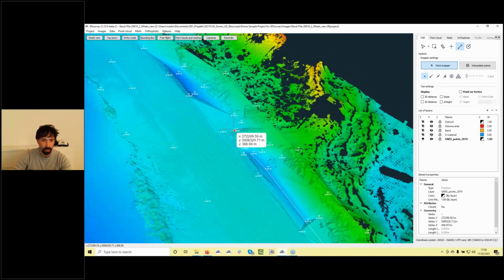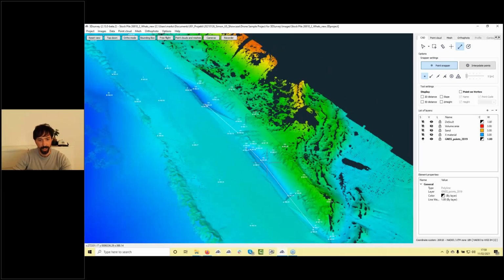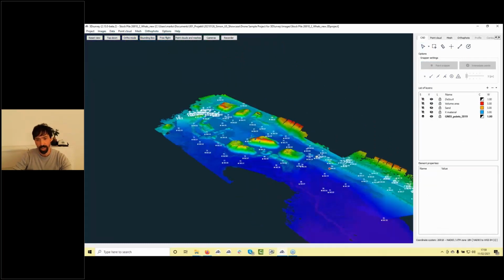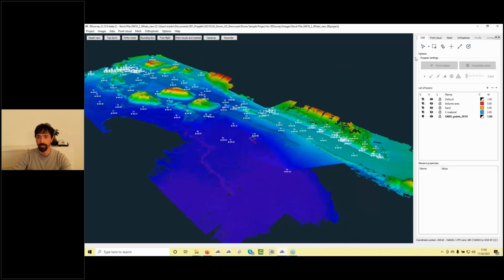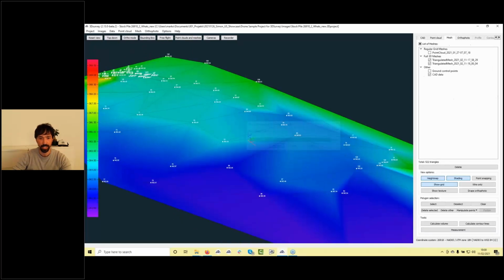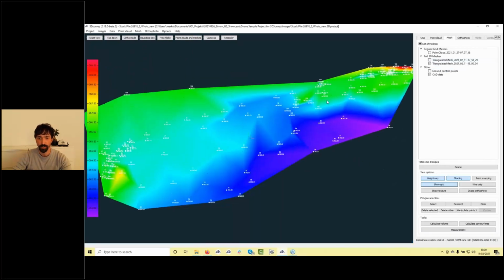So, oh, sorry, 2 lines. Okay, just to see the effect. So I actually create two break lines, and if I go again and do the triangulated mesh from CAD, now I have also those two break lines. Turn off the previous model.